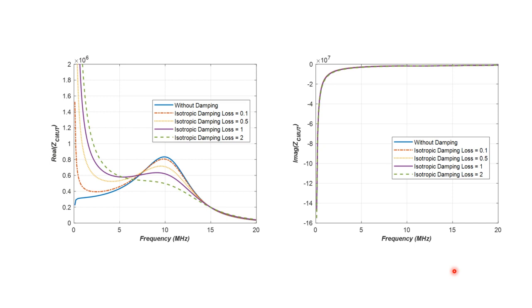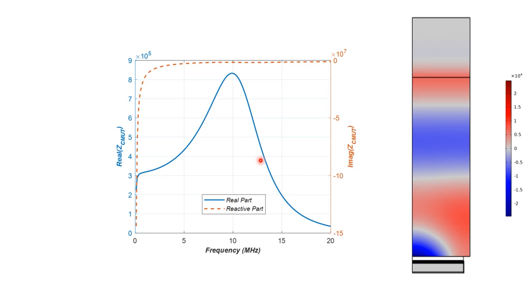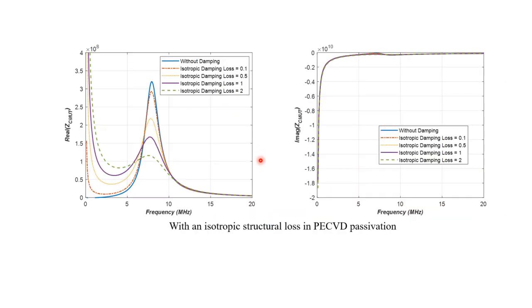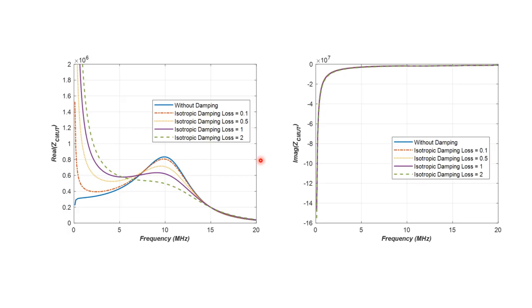But if you increase the loss like we did for the single element, the same trend occurs. The bandwidth is high and becomes larger if the loss is more, which is expected, and those dropping frequency characteristics become more and more apparent. So this is for the 1D array. You see a large impedance, about 2 megaohms, but this is for those frequencies. If you consider DC, at low frequencies, it's not that much. It's about 800 kiloohms. So this is for the single cell, and this is for the 1D array.